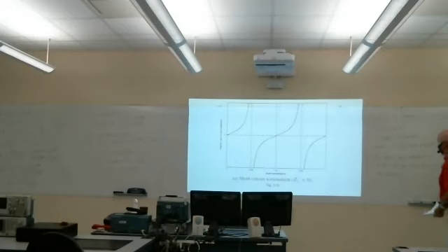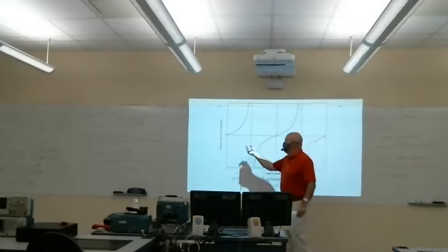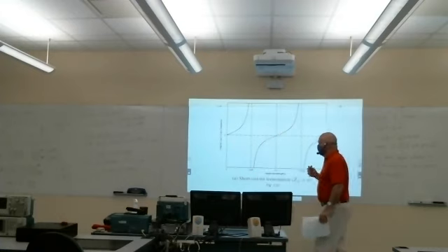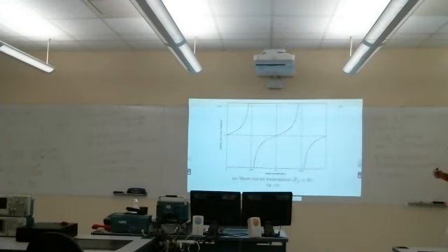Now, it doesn't have quite the same frequency dependence as a real inductor. A real inductor is j omega L, right? This is j times this thing. There is frequency dependence in here due to beta, but it's like the tangent of the frequency. Now, over a short distance, tangent of omega is approximately proportional to omega. So over a short distance, maybe length less than lambda over 10, this acts like an inductor.